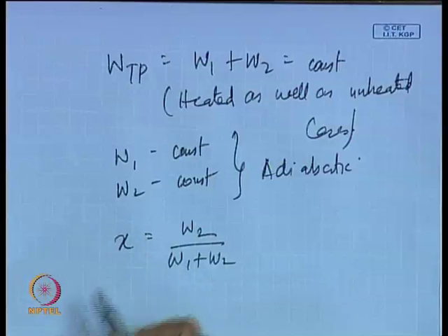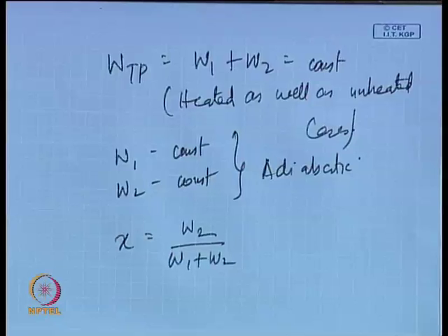But remember one thing, alpha is not a measurable quantity, but x is definitely a measurable quantity. It can be measured from heat transfer or heat balance equations or enthalpy balance equations. In the last class we had already mentioned that if we know the heat flux, if we know the amount of subcooling of the inlet liquid, we can find out x. And in other words, if both the liquid and the vapor are in equilibrium, under that circumstance also we can find out x. So, x is definitely not a non-measurable parameter, it is a measurable quantity, or it can be derived from measurable quantities, unlike alpha.